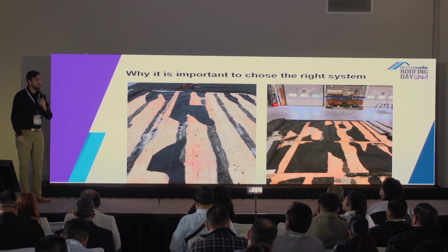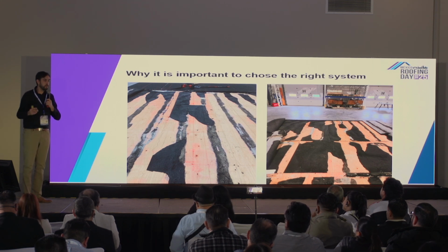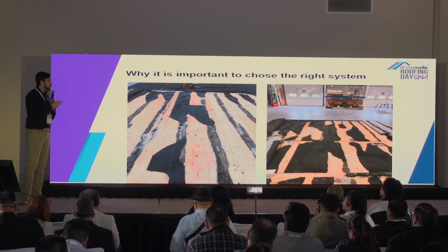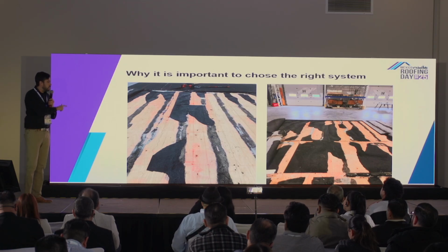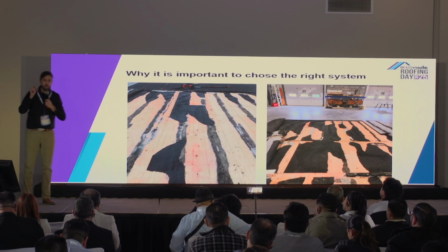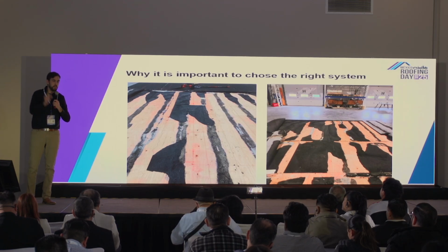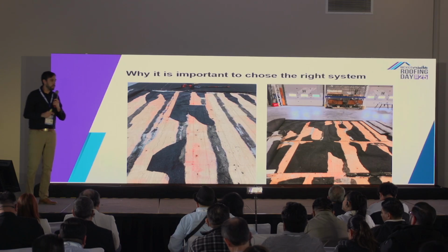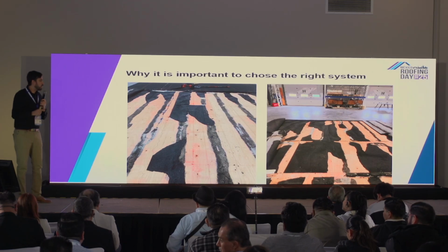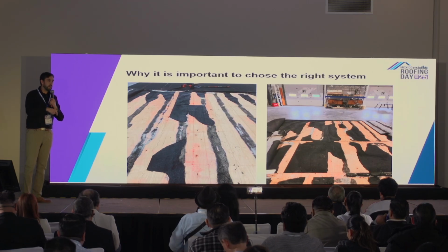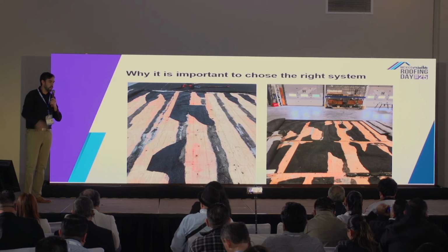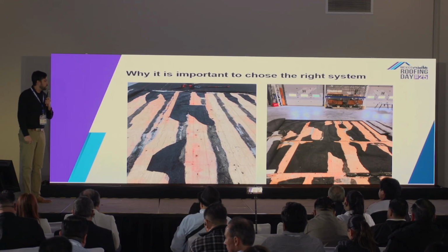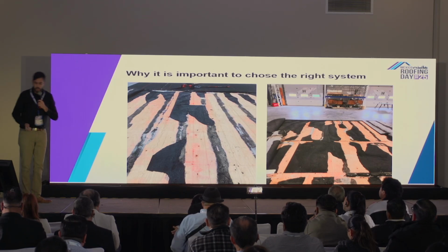They want to have the best system, so keep in mind that this is what's being done. So if you see that the width of the adhesive needs to be a certain amount, or the coverage rate, and you don't hit that, most likely you're going to end up like the pictures you saw at the beginning of the presentation. I hope that makes sense.